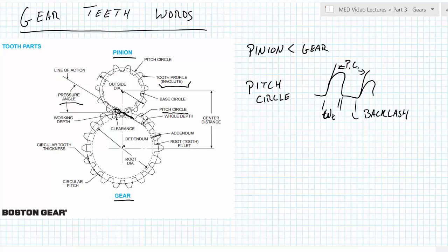And it's the space between that allows a tooth to come into that space and then leave that space. And you can have gears that are called anti-backlash gears which reduce the amount of noise and vibration between those, but they require higher precision in mounting. So the more backlash you have, the more flexibility you have in allowing those gears to wiggle around a little bit. If you have a very low tolerance for backlash, then you're going to need much higher specifications on your bearings and shafts.